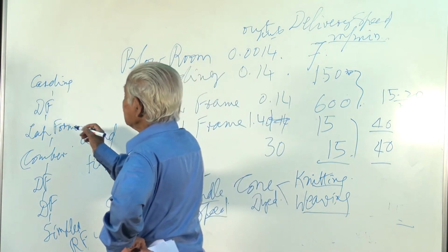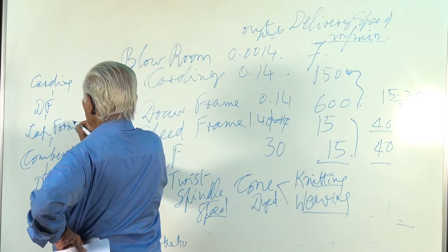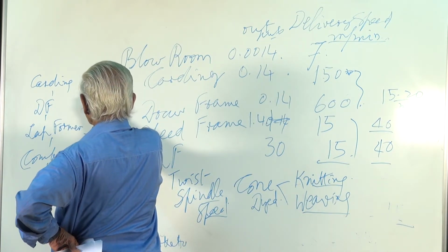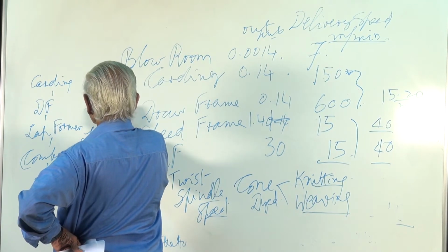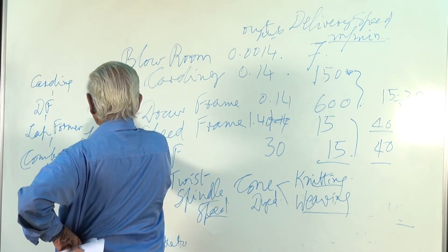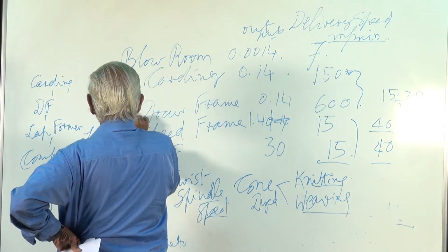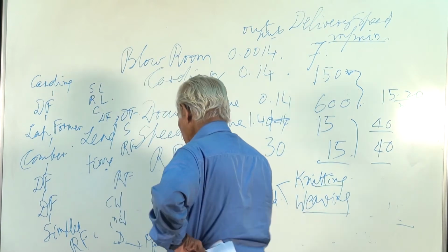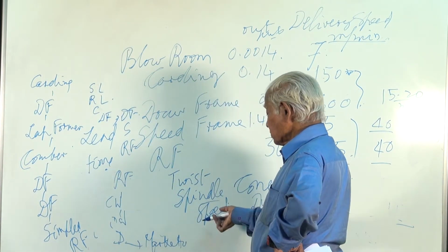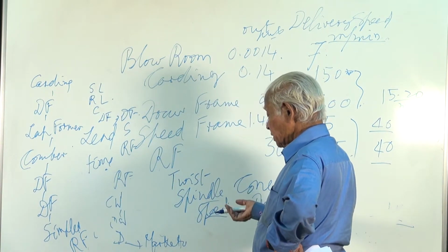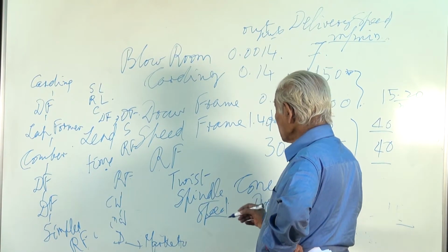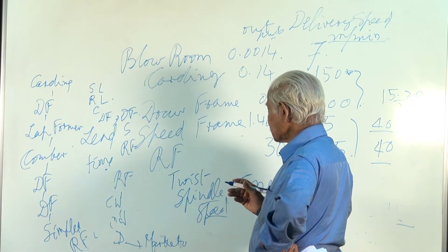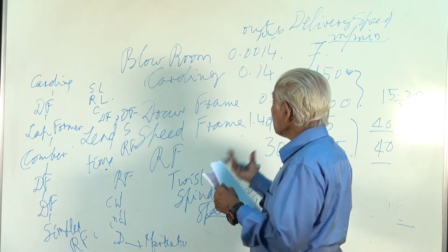And there is also another change. Suppose the mill has, after the card, it goes to a sliver lap machine, ribbon lap machine, and then comber and draw frame, and simplex and ring frame. Then combing also can be, doubling also can be done, either by a 2-for-1 twister or a doubling machine, as the case may be. A 2-for-1 twister means for every one turn, two turns of twist are inserted in the yarn, which is quite economical.